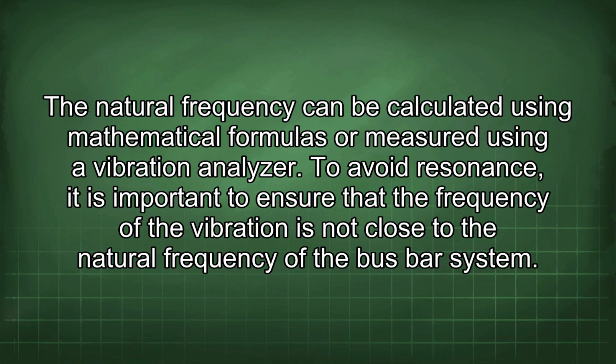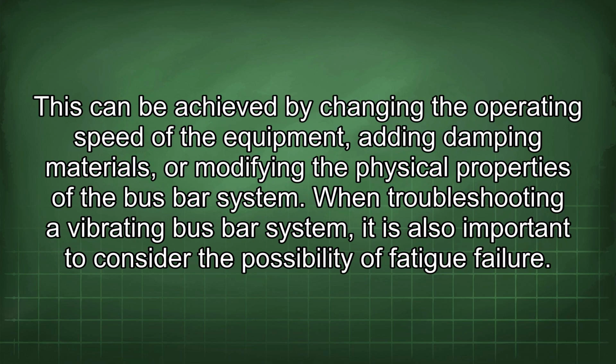To avoid resonance, it is important to ensure that the frequency of the vibration is not close to the natural frequency of the busbar system. This can be achieved by changing the operating speed of the equipment, adding damping materials, or modifying the physical properties of the busbar system.